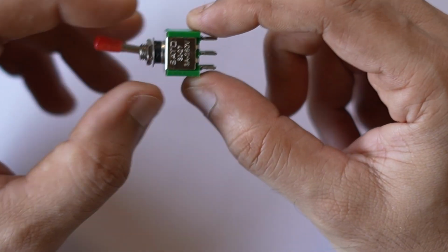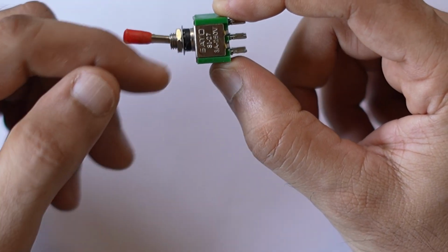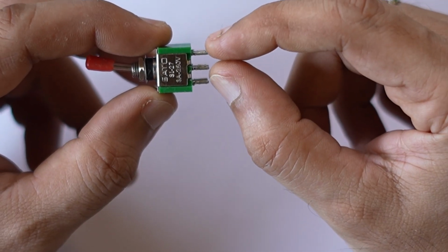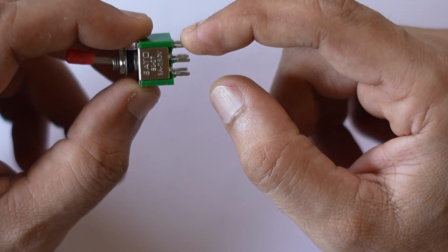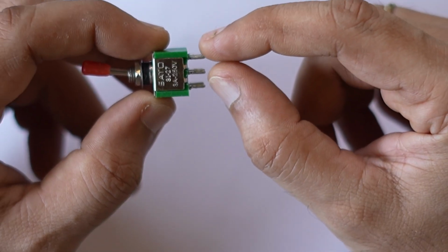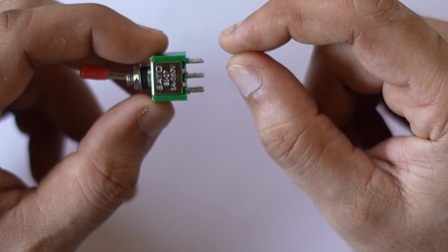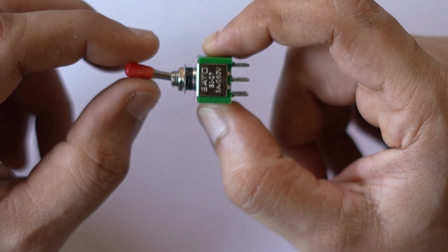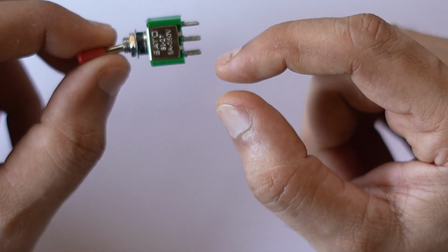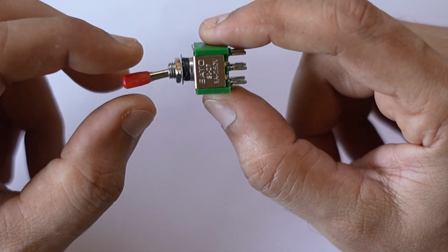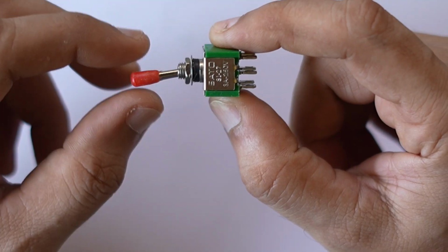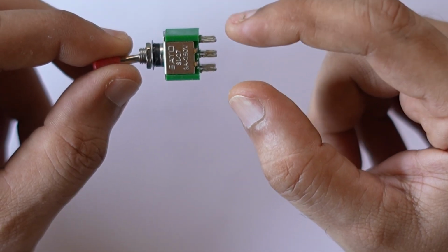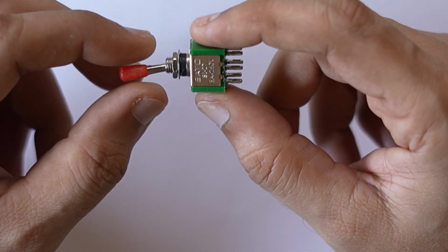And then when you toggle the lever at the top, the top pin and the center pin are connected to each other. Sometimes that logic is reversed, so it's always good sense to actually toggle it and use a multimeter to check which pins are being shorted. And then if you toggle it in the other direction, the center pin and the other pin gets shorted. So that's an on or that's an off, or you can toggle between two elements in a circuit, for example.